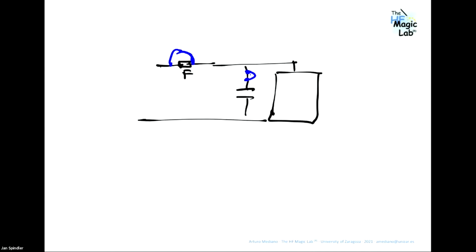When I short circuit the ferrite and I remove the jumper in the capacitor, there is no decoupling. When I remove the jumper in the ferrite and I connect the jumper in the capacitor, I have this filtering decoupling network. That's all. And this ferrite is something some people will recommend not to introduce. So my recommendation is to test in your application.